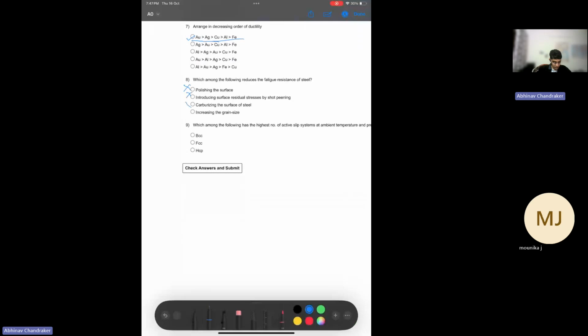Increasing grain size. If grain size is higher, then surface flaws form by extrusions and intrusions, and these happen because dislocations glide and move through your material through certain mechanisms. We have seen what dislocation structures are involved, and they reach the surface.